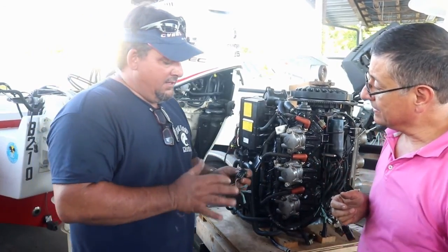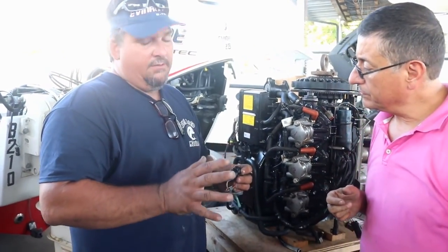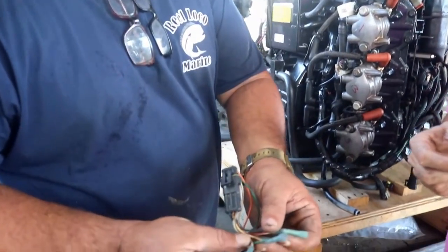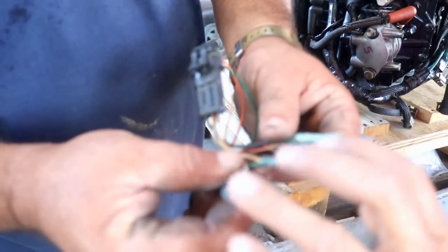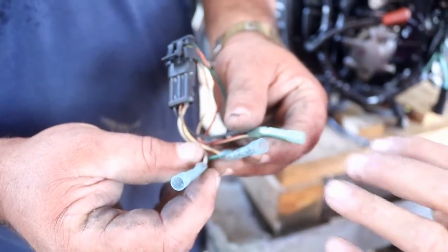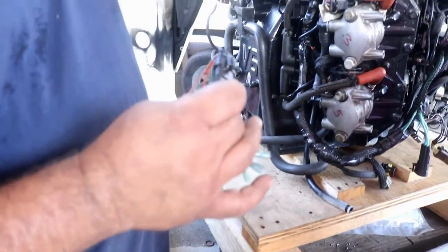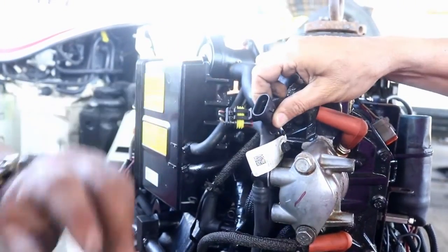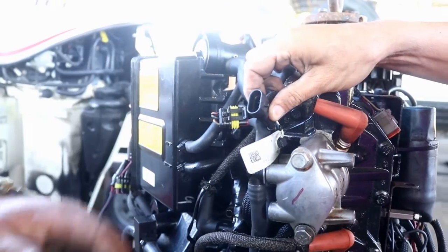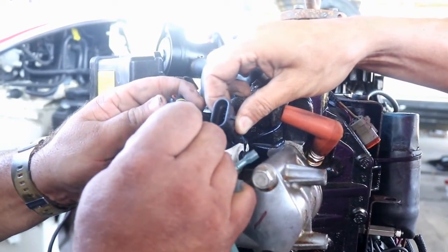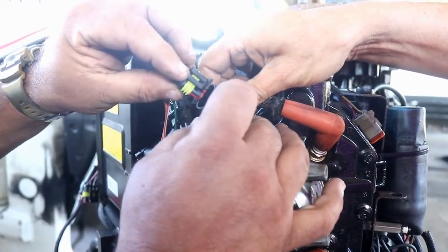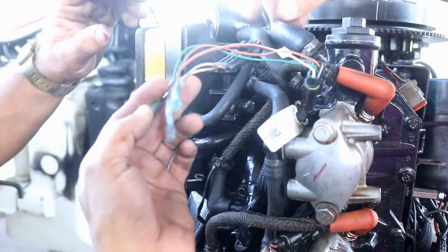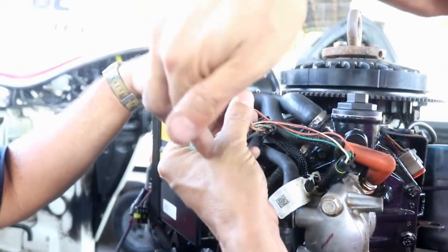So how I made this harness, and like I said, each individual makes their own harness. I made mine like this so I can put my meters in there to test for power, continuity, grounds. What I do is break the system apart. This is for the injector specifically. And then you put this in line, so you never interrupt the system. Correct. The system continues over there and you have access to connect your multimeter.